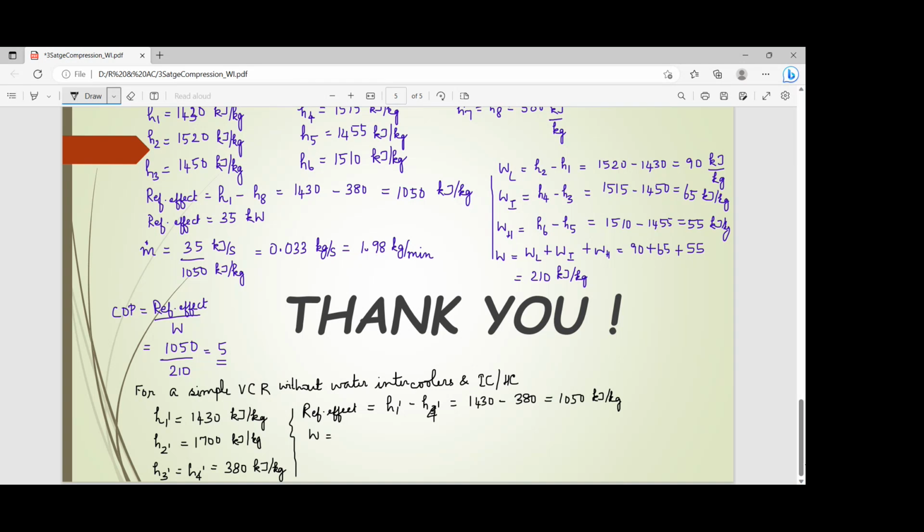But let's look at the work input, which is going to be H2 dash minus H1 dash, 1700 minus 1430. So that's going to be 270, I believe. Let's cross check that. 1700 minus 1430. Yeah, it's 270 kilojoule per kilogram. So what is the COP here? That is 1050 divided by 270. 1050 divided by 270 is 3.89. So that is the COP.